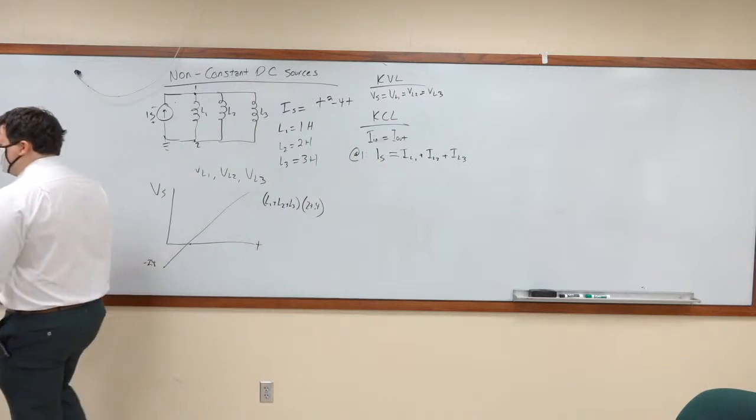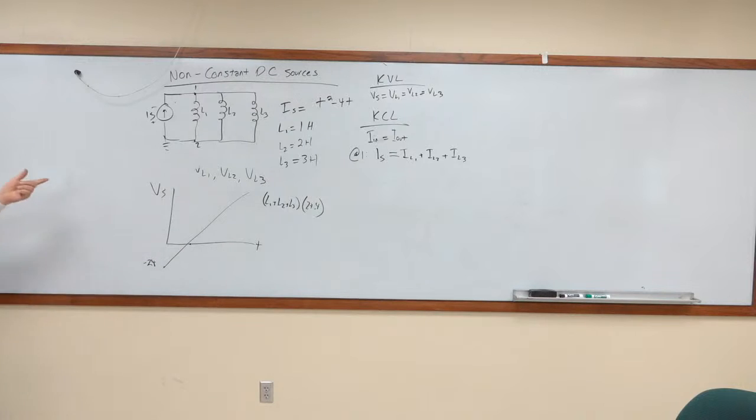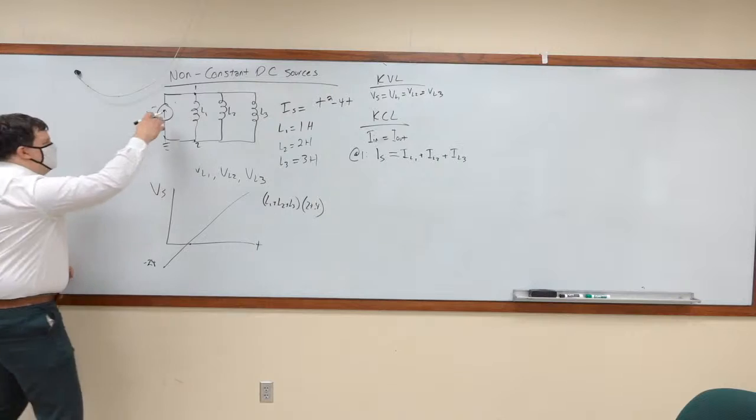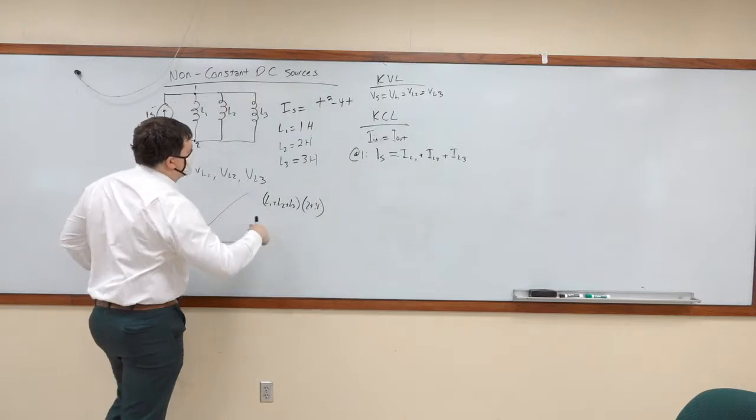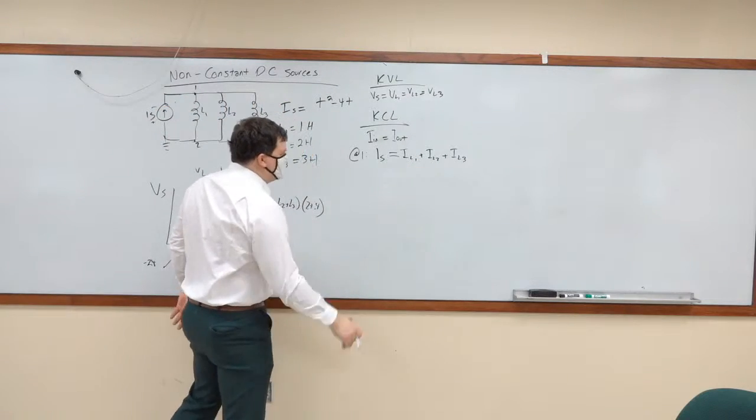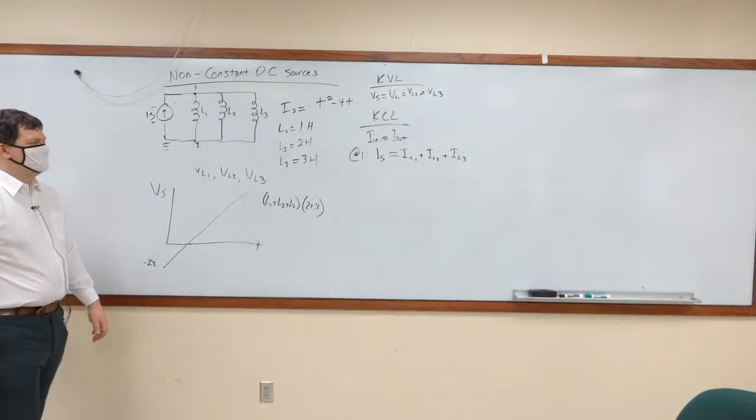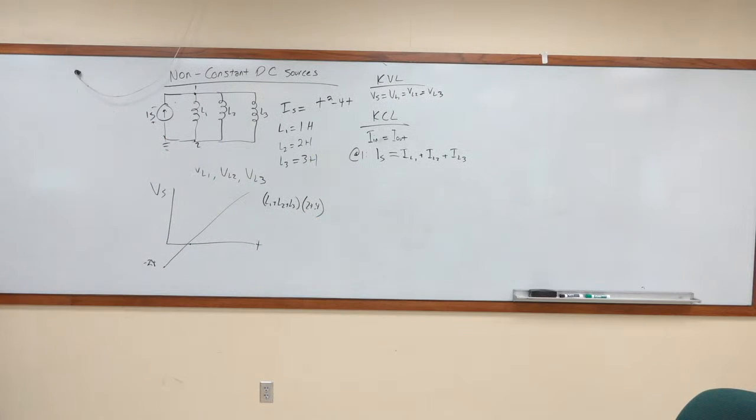Okay, and if we do KCL at node 2, we'll get the exact same equation. So we don't really need to write KCL at node 2. So doing KVL, we have 1, 2, 3 different loops. We get those equations. Using KCL, we have 2 equations, but both of them are identical. That's what we have to work off of.